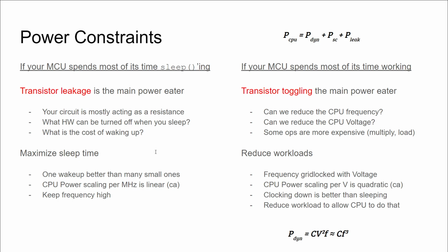So, looking at the always off type of system on the leftmost hand of the slide here, the only real cost is leakage, because there's not much going on in the system. At best, you may have a clock counter increasing every millisecond. If you want to reduce the power consumption of this system, you want to avoid doing what the Facebook app is doing. You want to avoid waking up. So if you can wake up less, you will allow the parts of the hardware that can go to sleep to stay asleep, and this is what you can do to minimize the power usage.